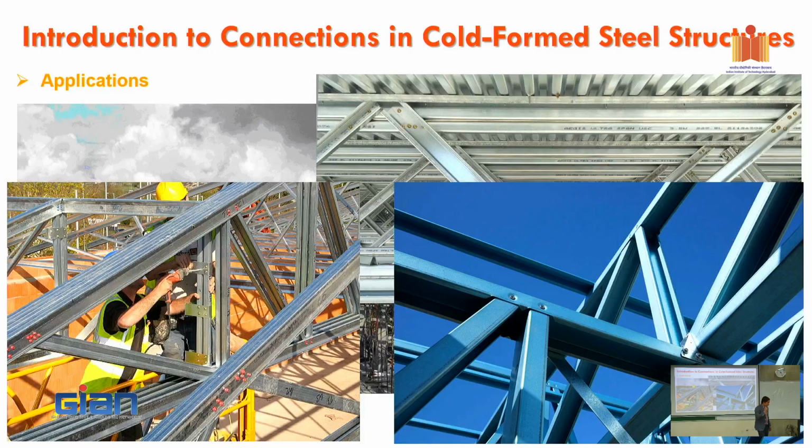Yes, a good question. There's two types of screw: one is self-tapping, and the other is self-drilling. This one uses dimple holes, and if they make a little pre-drilled hole, they use a self-drilling screw. But if you have nothing and you want to tap in, they use self-tapping. The top bit of the screw acts as the drill, so they just zoom in and go in easily.